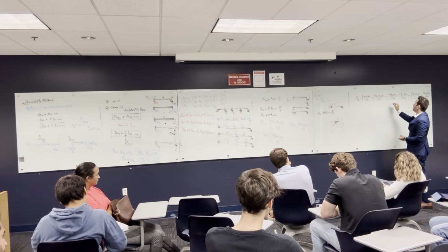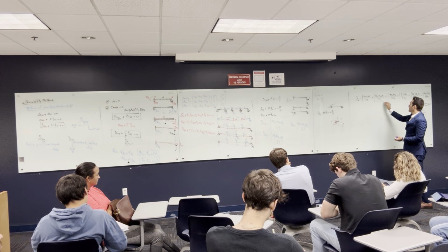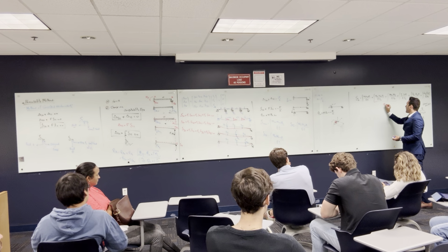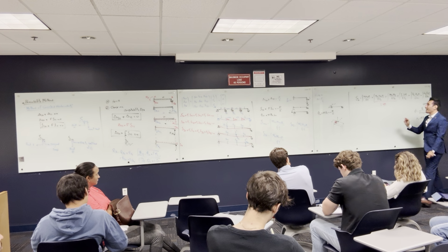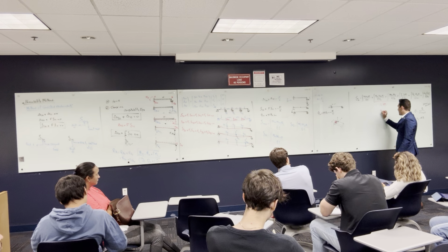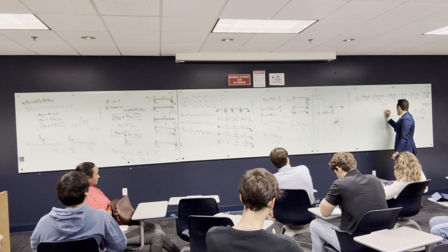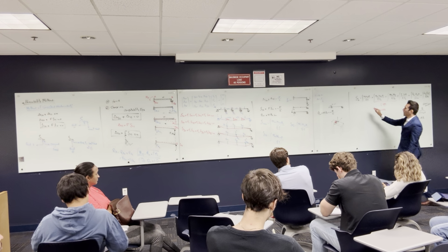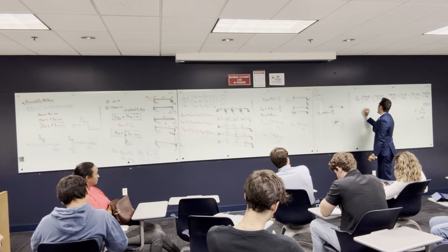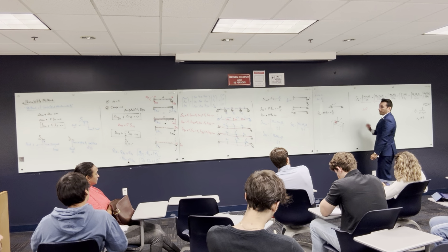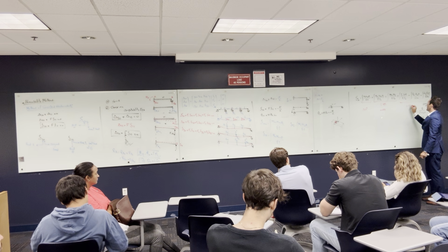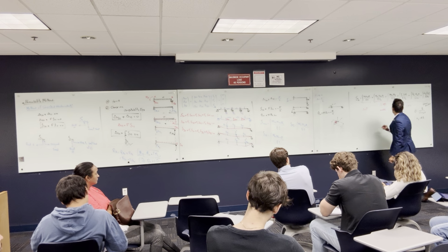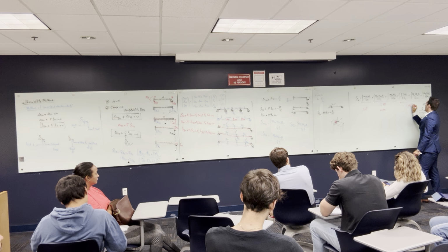You will find that the deformation that comes from the moment is around 95% of the total deformation of the cross section. Like I got the deformation in the cross section 0.0125. This one gave me a deformation of like 2 multiplied by 10 to the power negative 5, and this one gave me like 3 multiplied by 10 to the power negative 5, and this one negative 5.